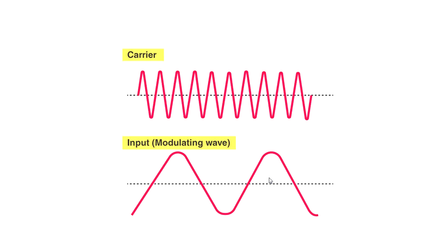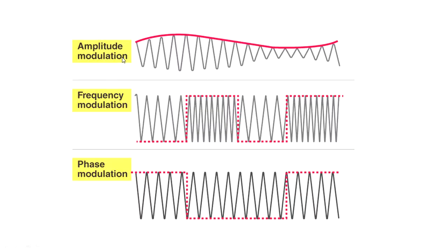So this is just an illustration of whatever we have seen so far. What is modulation? You have an input signal, you have a carrier. So this is your input signal here and you have a carrier signal here. In amplitude modulation, you are going to vary the amplitude of your wave. In the case of frequency modulation, see here, you are going to vary the frequency of your wave periodically. In phase modulation, yes, you are going to obviously change the phase of your modulated wave. The frequency remains the same in the other 2 cases.